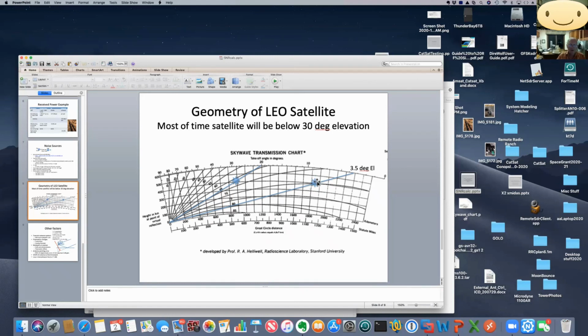At this altitude, you'll probably be lucky to get 2 north-going passes and 2 south-going passes a day. If you were orbiting at, say, 1,000 kilometers, you would typically get 3 north-going passes and 3 south-going passes a day. Plus the passes would be longer. So you just have to work the orbits out in equations and figure it out.